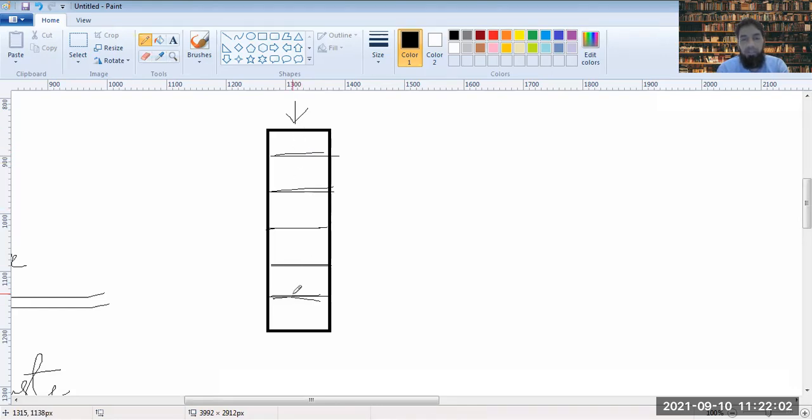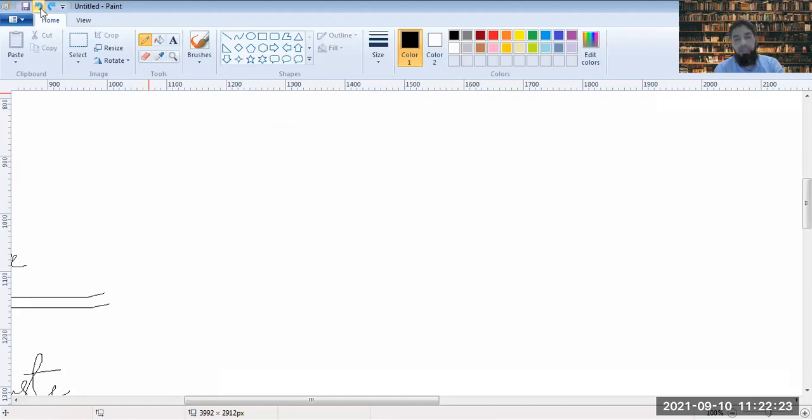So the concrete does not require shear resistance. So here we require more flowability, such that it settles down in layers, we require more flowability in the case of column. So this is the reason for different slump values in different situations.